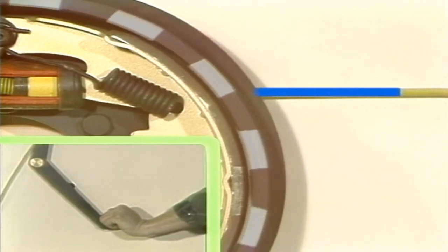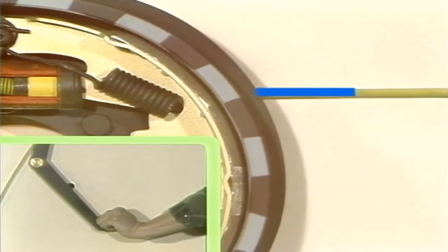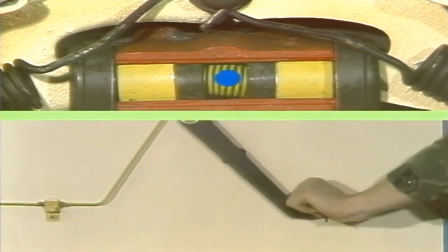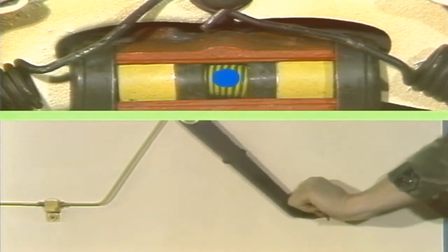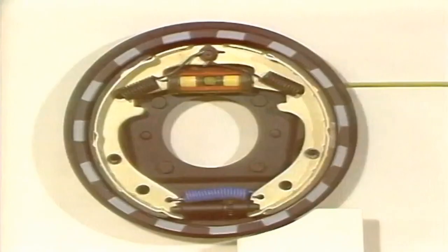The increased pressure in the brake fluid presses against the air bubble and it shrinks. Let's say the air bubble gets forced into the wheel cylinder. Plainly, the full force generated by the master cylinder piston is not being transmitted to the wheel cylinder pistons, and brake pedal action feels spongy. It takes a lot more pedal pressure to bring the wheel to a full stop, and the air can cause uneven vehicle braking.